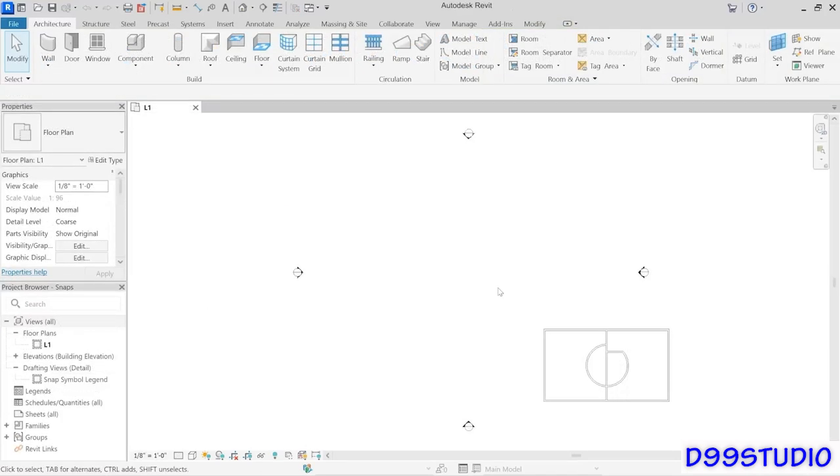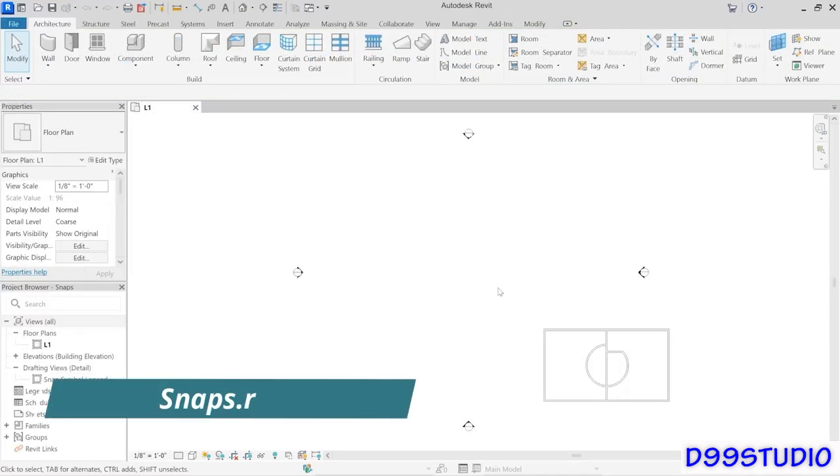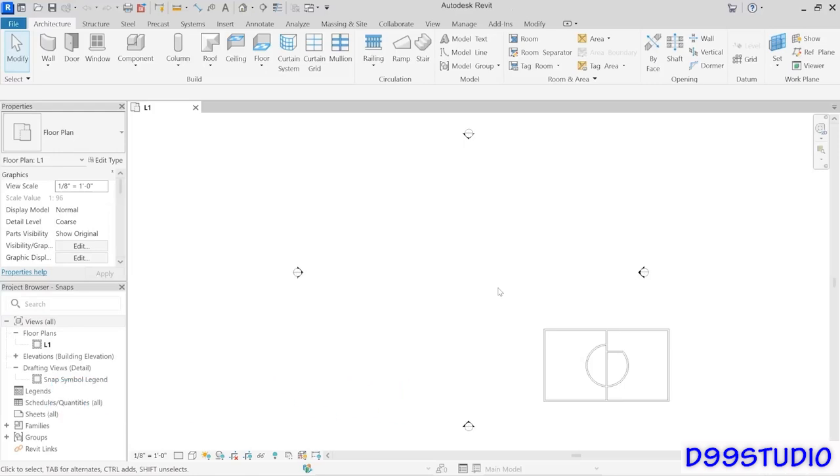In this video, we're going to talk about snap behavior. There are two kinds of snapping that we have in Revit. We have increment snapping and we have object snapping. And so I'd like to illustrate both of those. And both of them are similar in function. They help you build your model with more precision without necessarily having to input exact values in order to do so. So let's start with increment snapping.